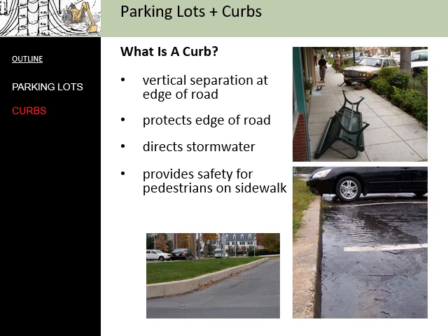It also directs stormwater so that we can put water where we want it, and we have a couple of goals for that. Number one is normally safety. We don't want water to run where the cars are going to be driving, especially where they're going to be turning, and we want to avoid water where the pedestrians are going to be walking.